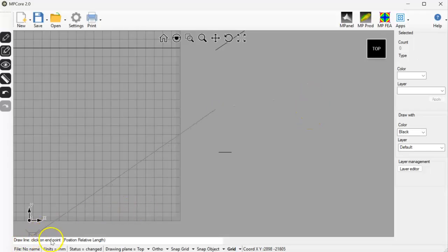This time we'll define the finish point with the relative command. So we hit R for relative, and we're asked for the delta, as in the difference, in X, Y, and Z. Z being the three-dimensional vertical component.